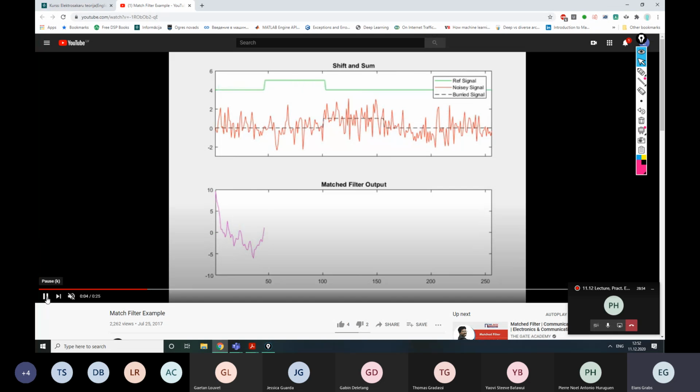Some values are calculated for output. Now we are getting close to our signal. And now they match completely, right? So that's when we have calculated the maximum value at the output of the filter. Now, as this signal continues moving around, the value will continue to decrease. And then we have the exact location where our pattern signal has been observed in this received signal.